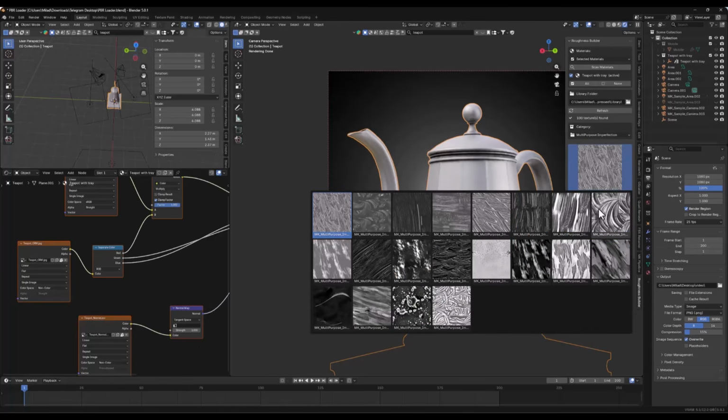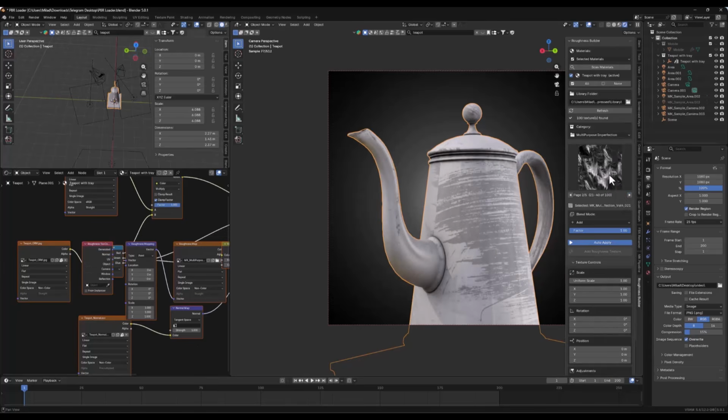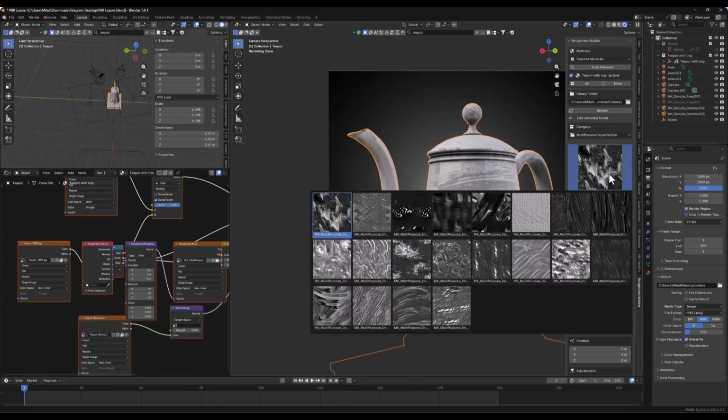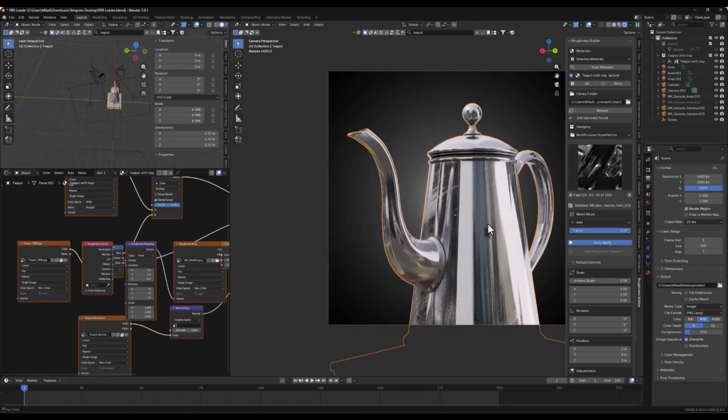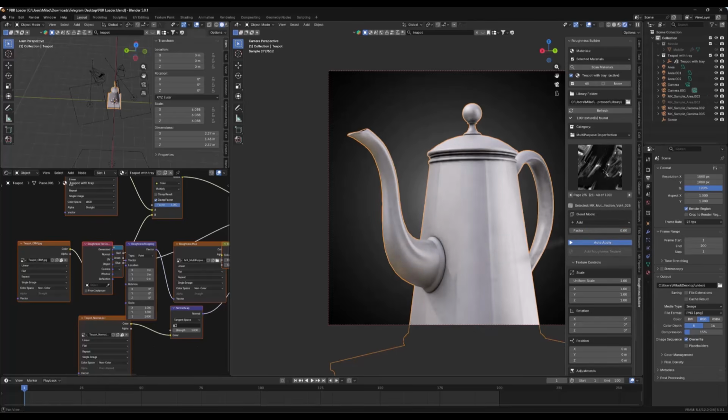Here, for example, I select something else, let another texture like this be selected, or another texture like this be selected. Now let's come here. When the factor is on the number 1, it means 100% of this is being used. When it is on the number 0, it means 100% of its own texture. When it is on 50, naturally, 50% of its own texture is used and 50% of our texture is used.